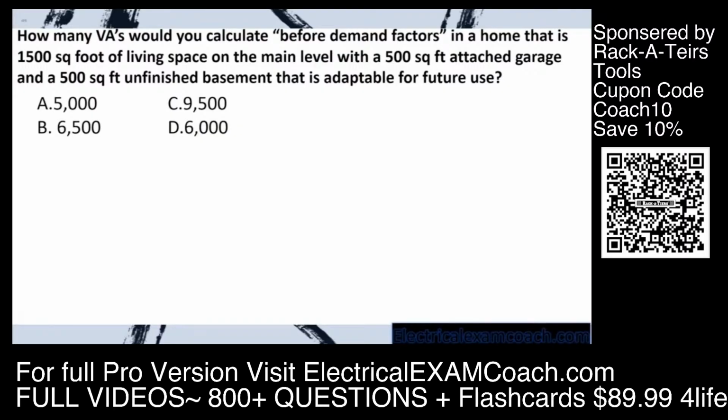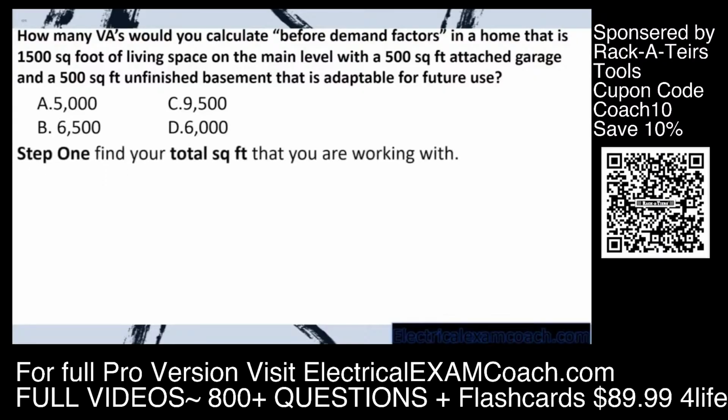How many VAs would you calculate before demand factors in a home that is 1,500 square foot of living space on the main level with a 500 square foot attached garage and a 500 square foot unfinished basement that is adaptable for future use? Step 1 is find what our total square feet that we're working with. So we have our 1,500 general.